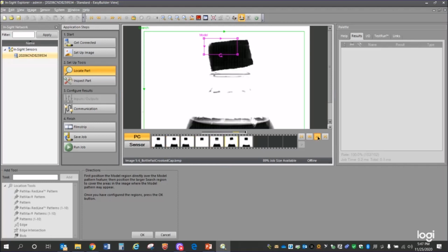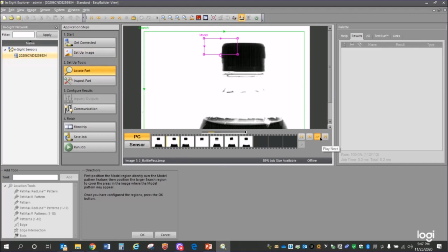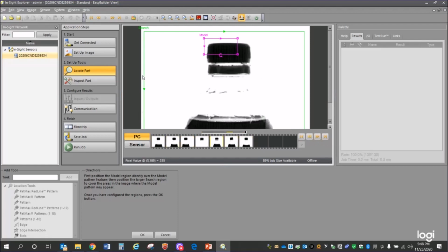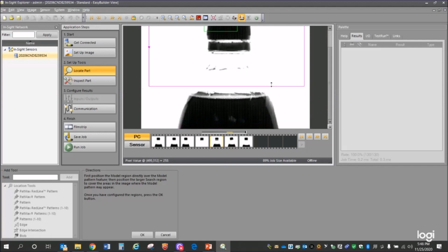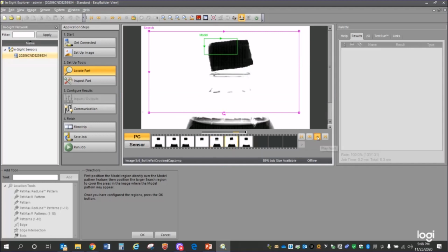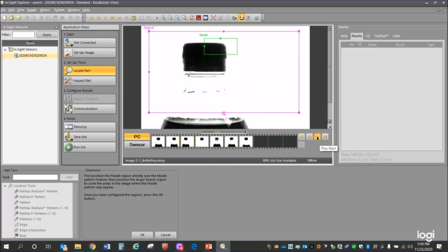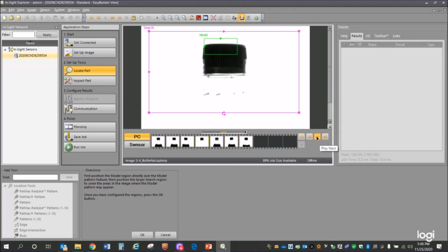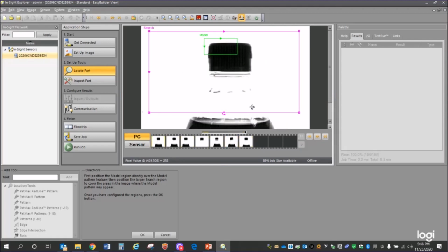So I'm going to build this based upon my best image, which is this image right here. But what I can tell you is my search area, the bottle never leaves that outside rectangle right now, does it? Now really, I should try to make that outside rectangle kind of representative of where I'd expect that to happen so it doesn't have to look as far. But I don't want to make it too small because I've only got 7 images here, and it's possible that in a future one it might be further to the left or further to the right, right?